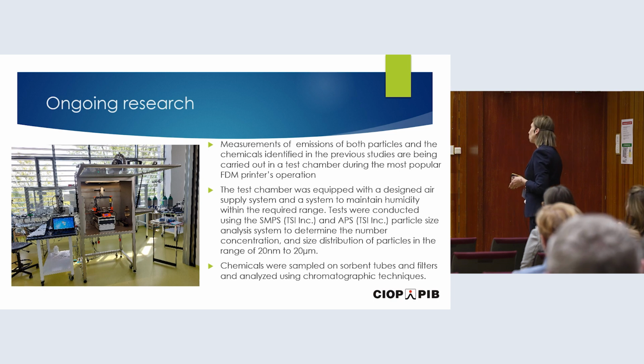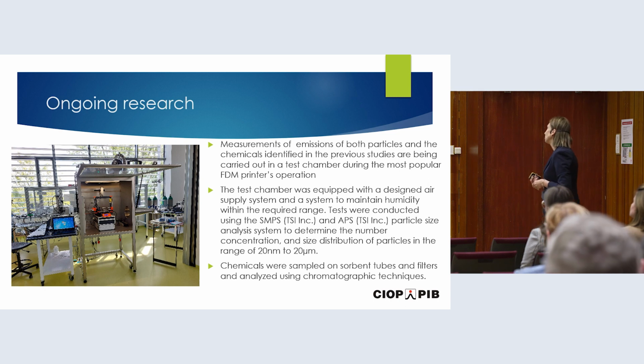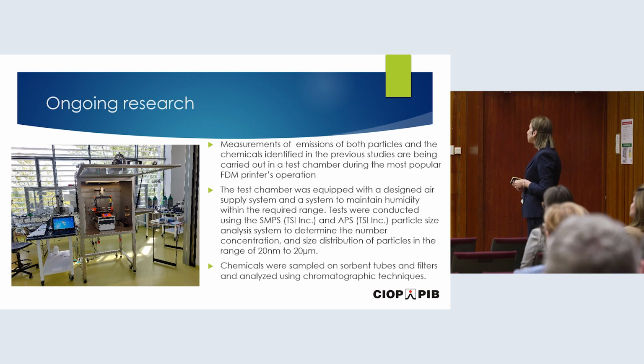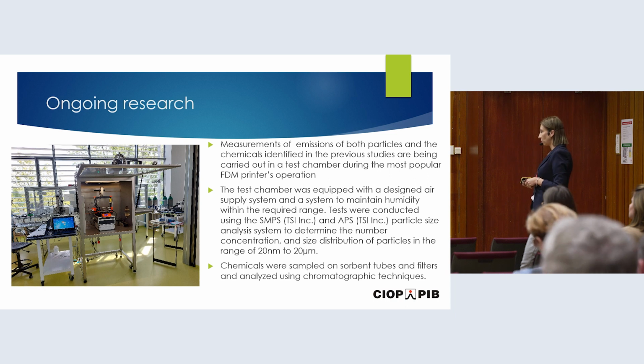That means we equipped the chamber with a designed air supply system and a system to maintain humidity within the required range. For our tests, we use two types of particle size analysis systems to determine the number concentration, and chemicals we are analyzing by sampling with different types of filters and sorbents, and then analyzing them chromatographically.